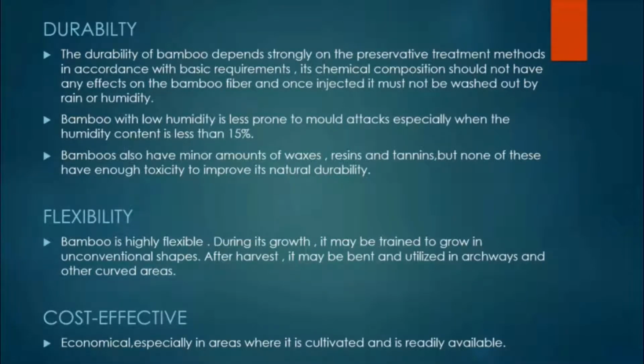Bamboo also has minor amounts of waxes, resins, and tannins, but none of these have enough toxicity to improve its natural durability. Bamboo to be treated with a preservative needs to be dry to facilitate penetration. Bamboo can be dried in air, greenhouse, and oven or by fire.